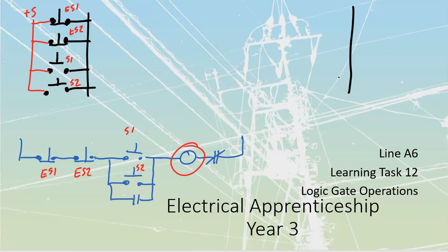Now, inside of here, there's a bunch of other stuff where we have to address and set stuff up, but it's not that big of a deal. Ultimately we're going to take this out to this component over here. This is going to be my coil, and then downstream of that, we're going to place these over there. So we're just going to create all of this in between. Is this easy for us to troubleshoot? Absolutely. If there's power here, the coil should be on. If there's power here and the coil's not on, the only thing it would be is my overload. So it makes for some really simplified troubleshooting.